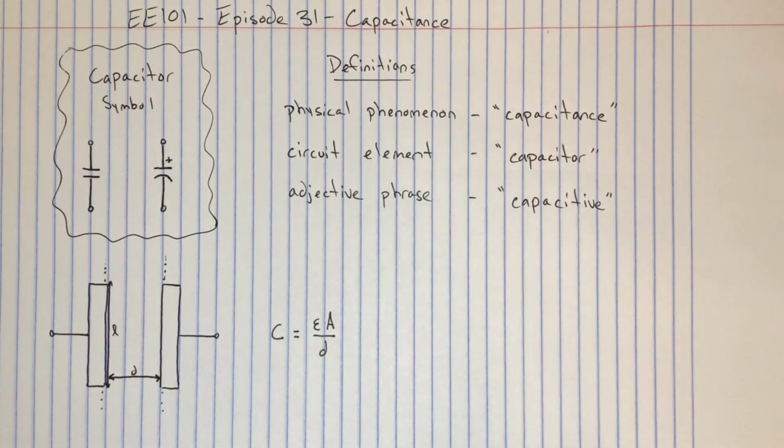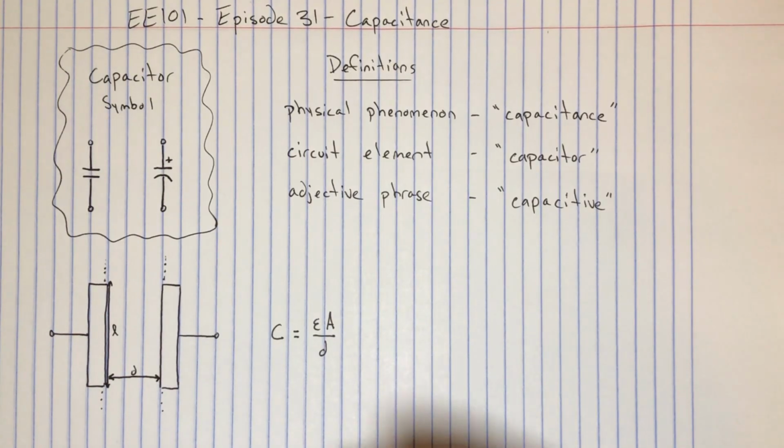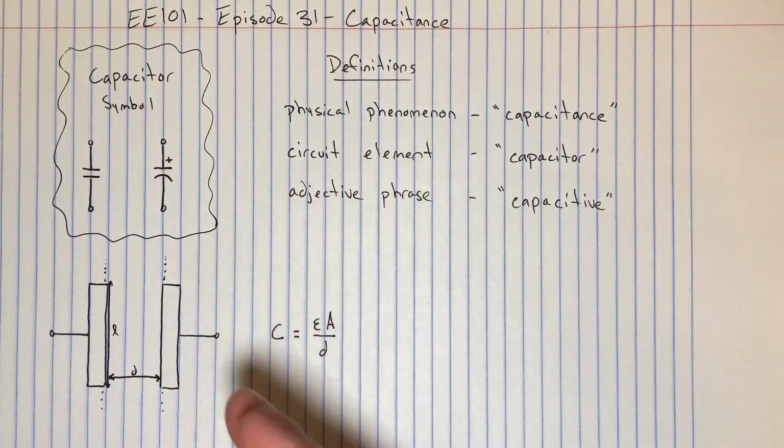With all those assumptions out of the way, we can finally analyze this formula, which essentially tells us three things about the capacitance. The first is the proportionality to the area of the overlap shared by the conductors. This means the more conductive material there is forming a gap with the other conductor, the more capacitance. And in this case, the variable A describes the area of overlap. As far as how that relates to this drawing, A is the product of the length and the width of the plates. The length L is pictured here as I've drawn it, and you have to imagine the width extending up out of the page and down into the page.